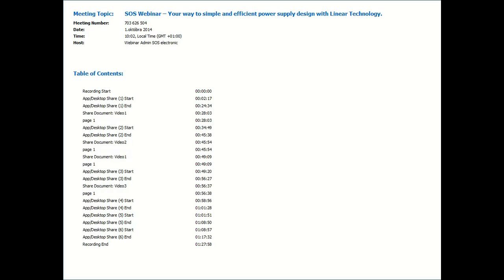Okay, thank you. So one of the proposals could be LTM 8026. That's the micro module which can, yeah, the output is adjusted between 1.2 volts and 24 volts. On the input, however, we have between 6 volts and 36 volts, and the output is 5 amps. So I will repeat: LTM 8026.